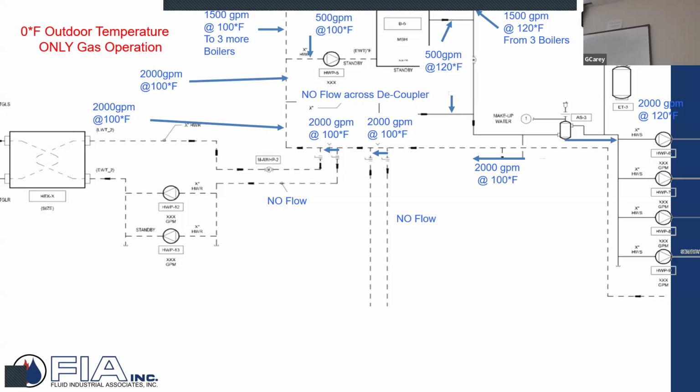Well, now you start applying that they weren't even thinking about 50 years ago, 60 years ago. So they realize they're saying, look, between this point and this point, if it's like 1 foot, 1.5 feet of pressure drop, it's fine. Yeah, because you're dealing with 50, 60, 100 feet of pressure drop on your system, it's fine. It's just more about minimizing so that you just don't want pumps with different capacities in series fighting each other. So, yeah, that monoflow building, yep. Design, yes.